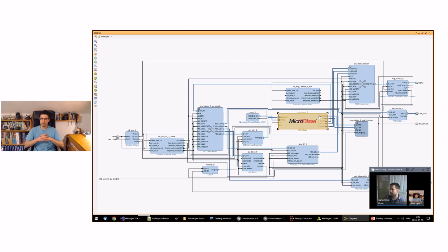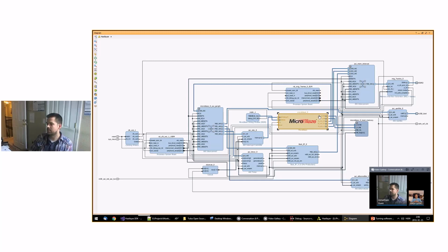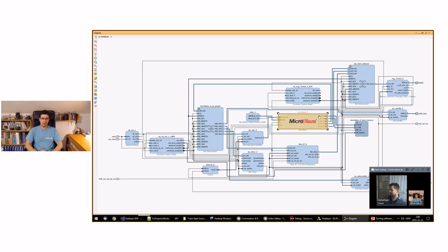So every time you run the .NET application, you've precompiled the VHDL and you just pass that into the FPGA that's communicating with that MicroBlaze build that you're showing there, or is that all built and loaded into the FPGA every time? You just need to do that once. Until you power off the FPGA, it will keep the configuration, because by default we don't put the configuration onto the flash, it just goes directly to the FPGA.